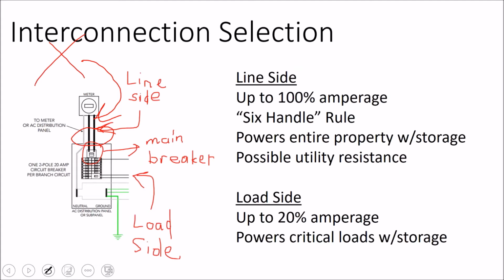And the answer is, yeah, you can do that, but you need an energy management system on site to do that. So you don't just need a generator and a battery, but you need a battery inverter that can act as the controller. Because if your generator and your solar array are not separately derived, they're going to try and fight each other unless there's a control system saying, okay, we have the storage capacity for any surplus power to go into our depleted battery bank.